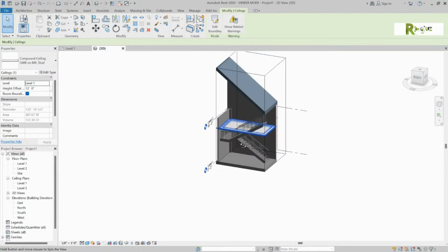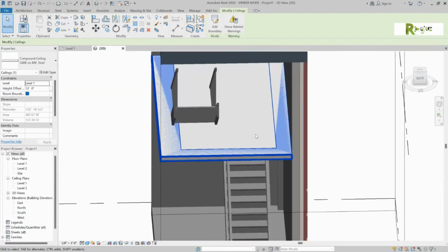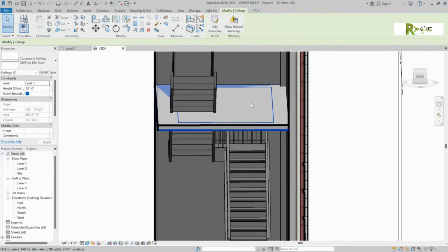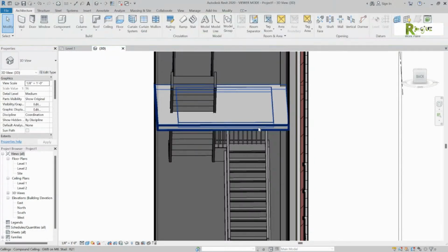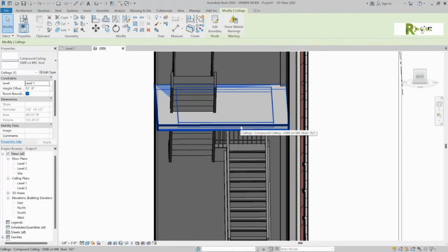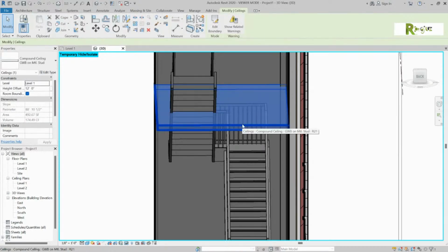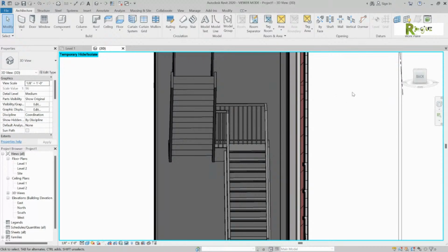You should have a hole carved in there if you didn't do what? Put 4 ceilings on top of each other. Yeah. So you've got the right one. Now, if you were going to try to find that when you have that kind of problem, what I typically do is pick that one that you know you got the good inside for and type in HH. And hide it, right? Yep. And then delete the object, rest. Now delete the other ceilings. Okay, now you got rid of them. There were only 2 ceilings there.